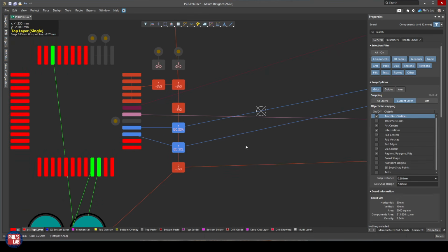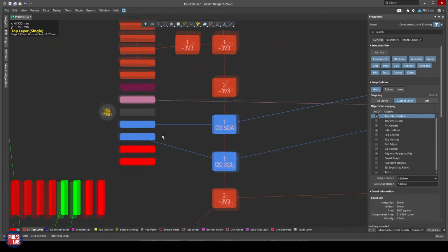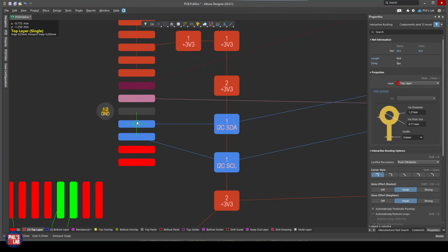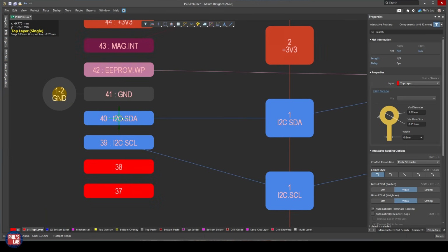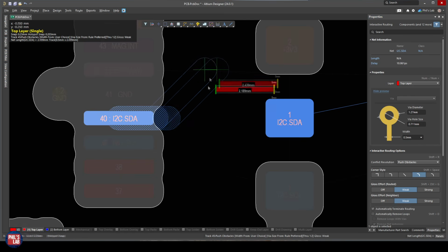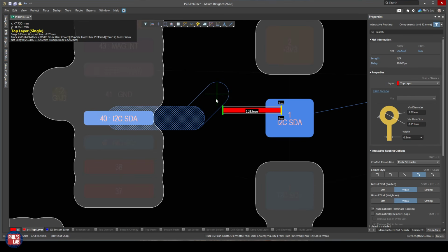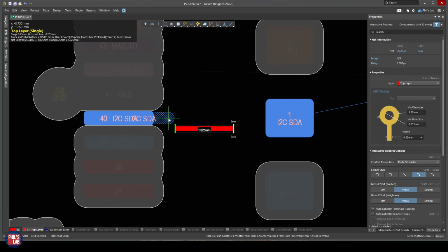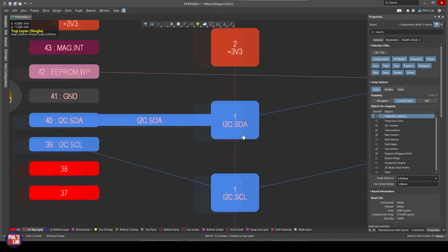Now, there's a couple ways of routing this. If we have multiple devices, if we just have a single device, we saw that just in the codec example. But for multiple devices, let's say I take the SDA trace and I just want to make that a typical signal trace width. So I don't want to do something excessive, for example, 0.5 millimeters or something that looks like a power trace. I want to make a fairly decently sized trace, and that of course depends on your board stack up parameters and so on, but something similar to, for example, the pad width of the MCU, so 0.25, 0.3 millimeters. I route directly out and into my SDA pull-up.